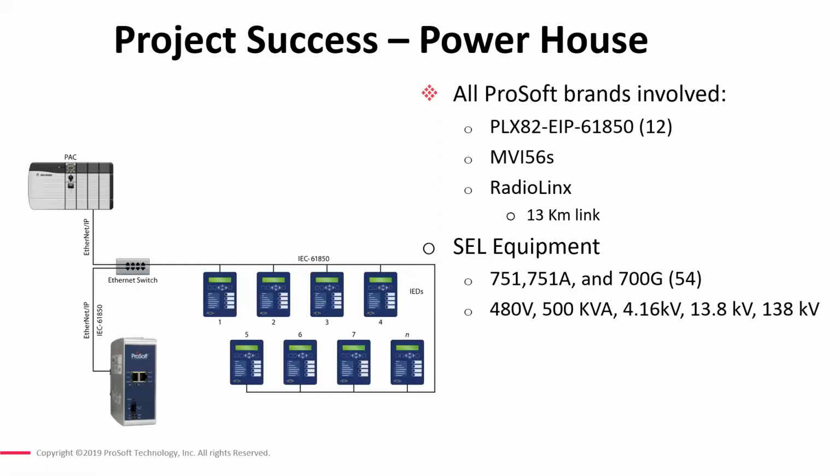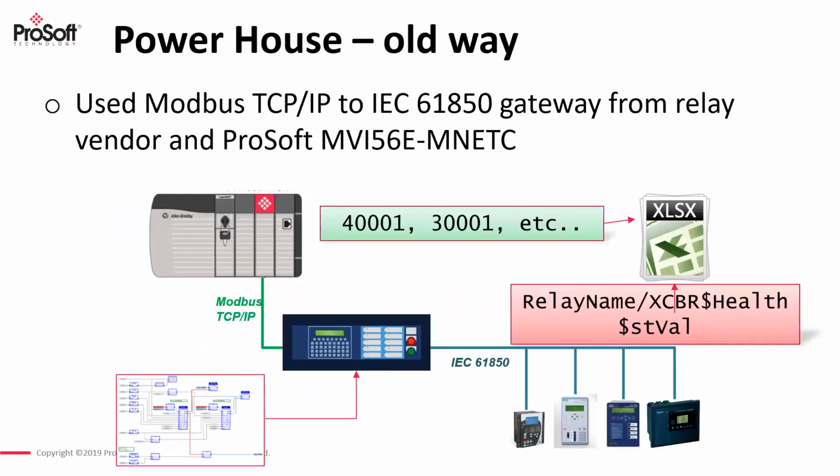The old way they were implementing these systems was using a Modbus TCP/IP network to a gateway device from the relay vendor, and then to get that data back into a Logix architecture, they were implementing the ProSoft MVI56E-MNETC module.